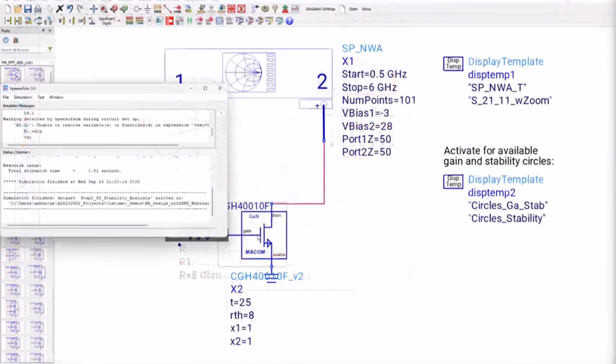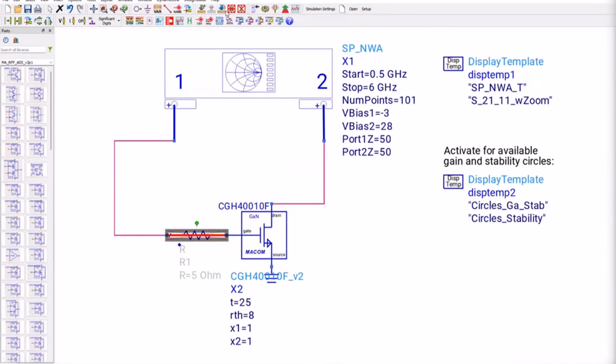With this, of course, the best way to induce stability is to put some resistor in action. And if you're doing a power amplifier, you will never put this resistor on the output side, because there your output power is already pretty high and you are producing a gain after a lot of struggle. So by putting a resistor, you will not like to eat away the gain you have, right? Typically you will find, even in the data sheet I showed you, that they were using a resistor in series with the gate and there was a shunt resistor with the gate bias.